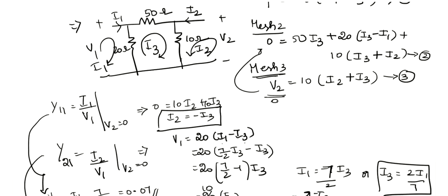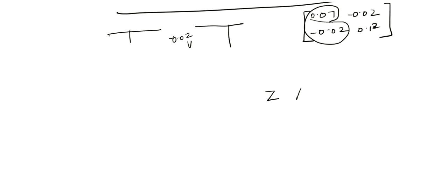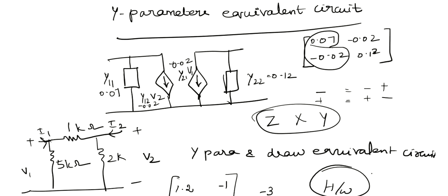And the equivalent network diagram of the two-port network for y parameters has two impedance boxes and two voltage controlled current sources. If it is having a minus value, it is a down arrow mark. Okay, these are the terms you have to remember at last. Clear? That's all about your y parameter. In the next video you can see the other parameters, that is called as... Thank you.